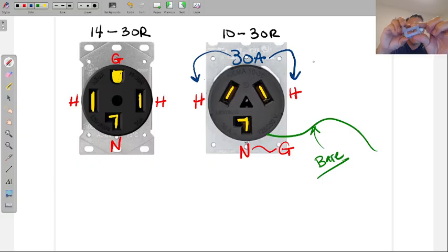It becomes a little magnet. That's why it's hollow inside. There's a little piece of metal here, and there are some contacts in front. When that gets energized, it becomes a magnet, and it closes the contacts. This one becomes a magnet, and this one gets pushed into it. When these contacts close, things happen. Next module, you'll work with one where we'll start a motor. Or when these contacts close, the dryer motor starts to go. Or the heater inside the dryer starts to activate. Or the oven. You guys get the point.